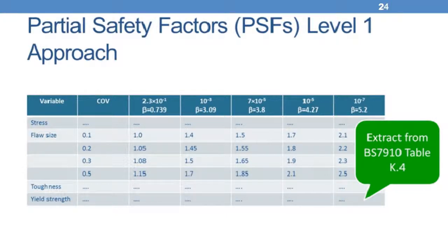This can be visualized by shifting the cloud of points in the previous failure assessment diagram slide around to achieve a particular proportion of points outside of the failure line. The application of this approach is very specific, though, to a certain loading scenario or geometry, so it has limited application, but within that application does provide a very rapid measure of reliability quantification.